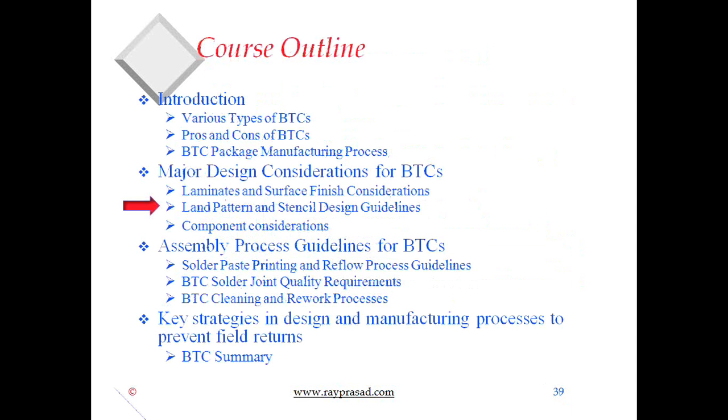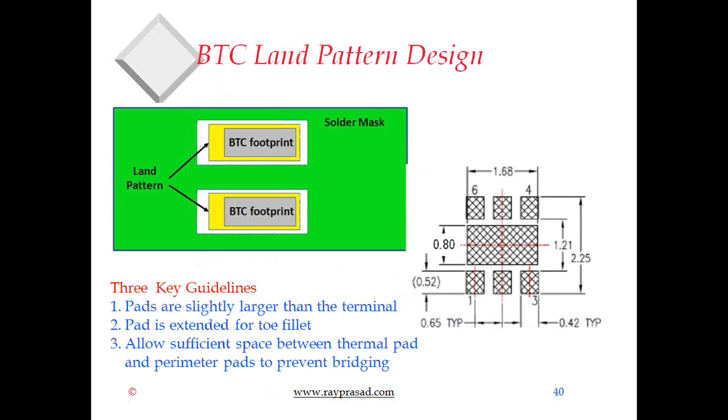All right. Let's get back to the land pattern design of the BTC, and then I'll open up for some questions. Here in slide 40 for land pattern design, as I mentioned earlier, whatever the pitch of these pads is, the pitch will stay the same.